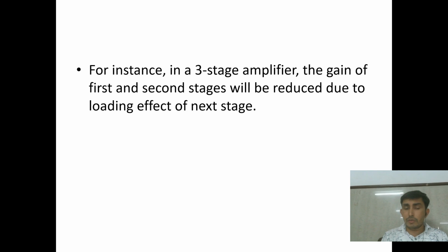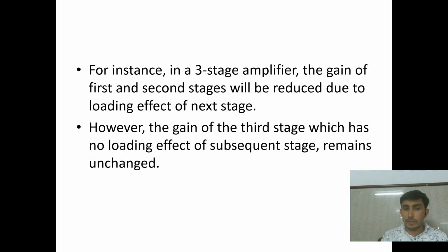For the third stage, if you are using a three-stage RC coupled amplifier, the third stage does not have any stage following it. Because of that, it has no loading effect. So we can say that the gain of the third stage, which has no loading effect, remains unchanged.